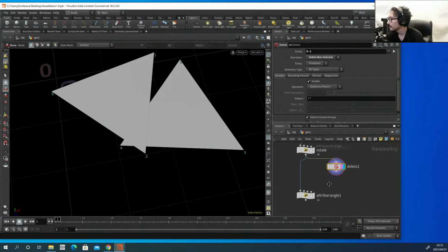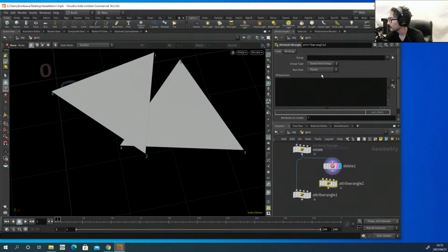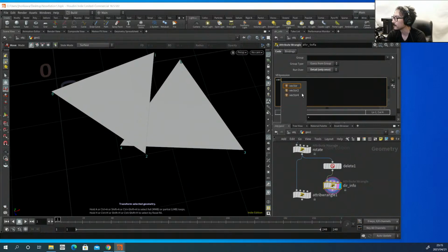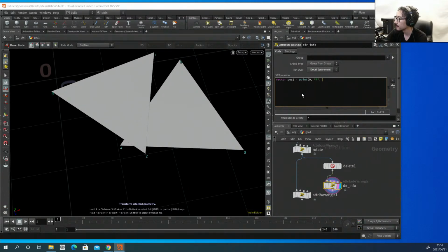Okay. Now let's retrieve that using attribute wrangle. Oops. Make it detail. Let's say direction info. So I just need to retrieve 2 point positions. First point position is v@pos1 = point(0, "P", 4) in this case, 4. This one here, 2. Other point position, vector pos2, is equal to point...